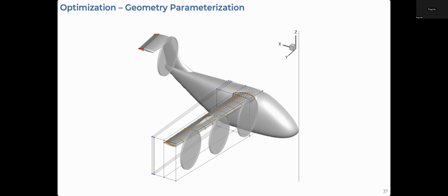And we can also pull up and down on the freeform deformation grid points to change the shape of the wing. Here's an animation of the optimization history for the cruise and maneuver flight conditions. You can see through this optimization that the maneuver has a much higher structural loading and is closer to failure. But we see, most importantly, that the sweep on the wing is removed, and we see an increased chord at the root and a decreased chord at the tip.